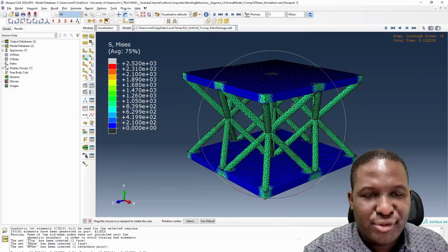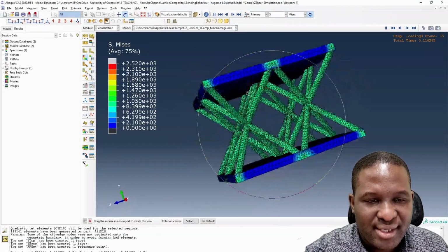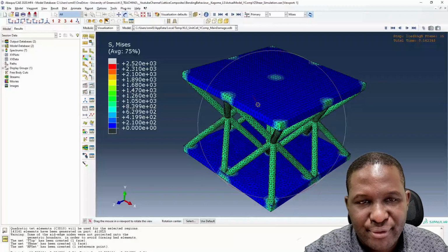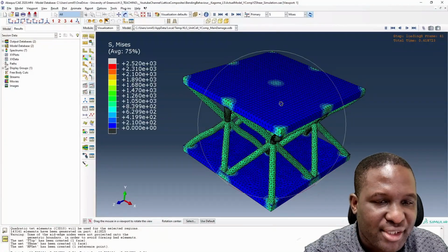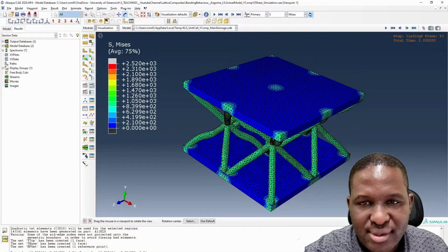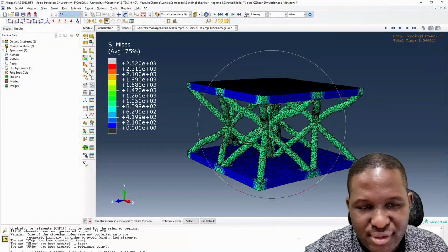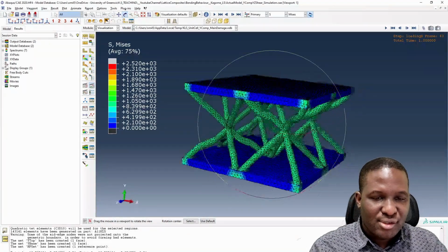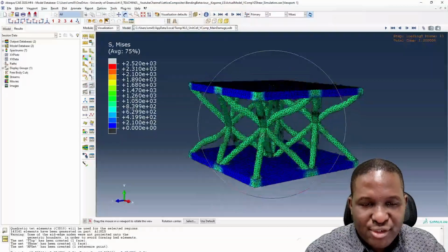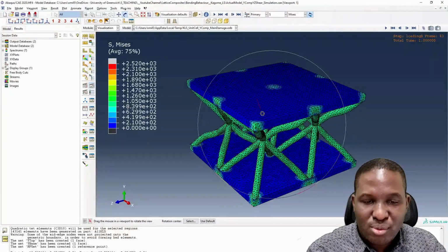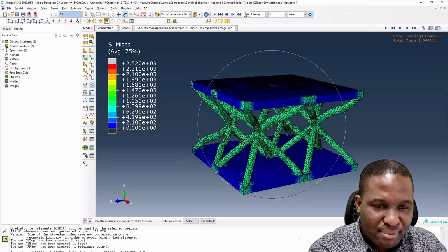Okay, so here are the results from the simulation. So what we're looking at here is the compressive behavior in the y-axis with damage incorporated, and then you could see the behavior, the simulation. So each of these fibers are obviously undergoing some kind of finite deformation. So if you keep increasing the deformation history, then this structure will probably ultimately start failing by buckling.